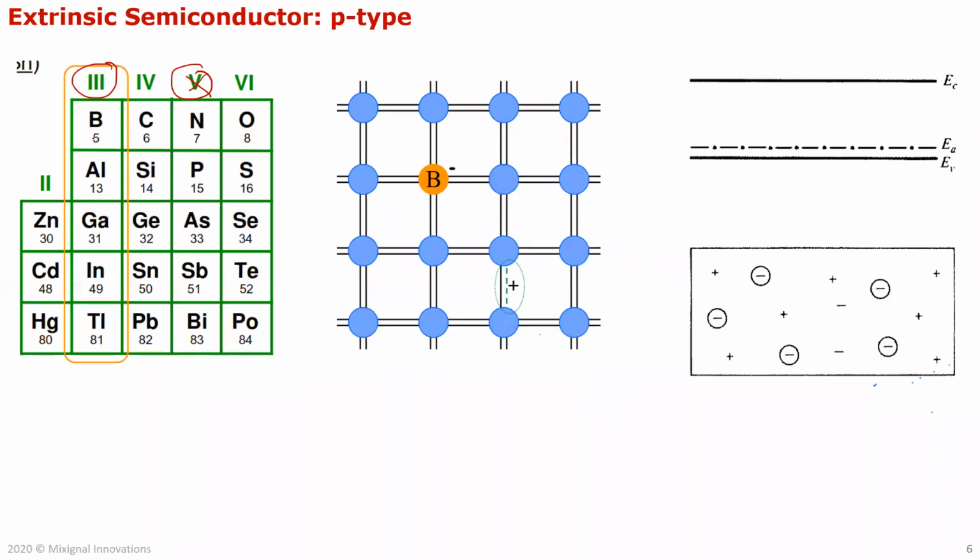So one popular one which goes well with silicon is boron. So if you take a little bit of boron, and again, the same concept here. So here boron is called the dopant. And when you're saying P, that means you have less than 10 to the power 15 atoms per centimeter cube of boron, or if people are saying it's P plus, then it is greater than 10 to the power 18 atoms of boron per centimeter cube. And it's the same concept. And for the p-type, it's the opposite in the sense that you have few borons for a large amount of the crystal lattice in silicon.